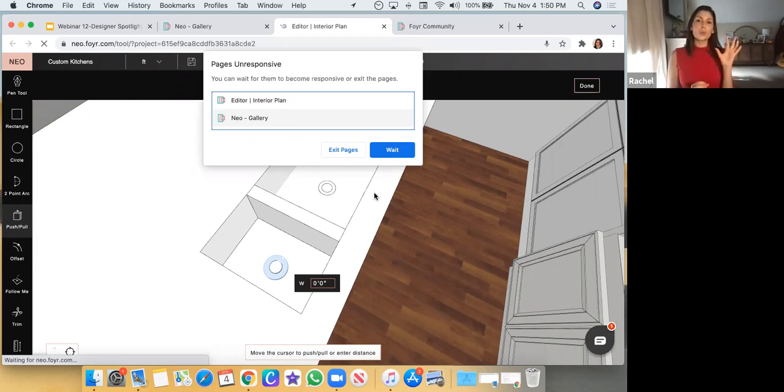Once you group products, you can not only clone them, but you'll be able to manipulate that grouping in the exact same way as anything else from the product catalog. So that's coming soon, and you're correct, you're not able to do that right now. Sometimes what I'll do is group products, clone them, move them, and then if I need free movement, I'll just ungroup them real quick. It still saves me time because they're all in the general location, and then I just fit them into place, but that's coming.